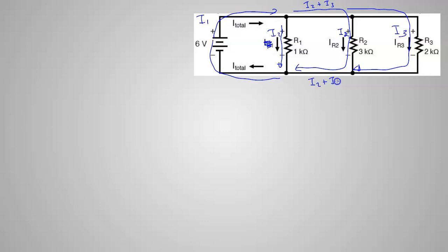But you can see that from this point, everything that goes out of here either goes on I2 or I3. And so it's probably better to not make that continuous there and there. Just call that little piece from this dot down to that dot I2. All of this can be I3, that's fine. That little piece should be I2 plus I3. There's kind of an art to doing this.